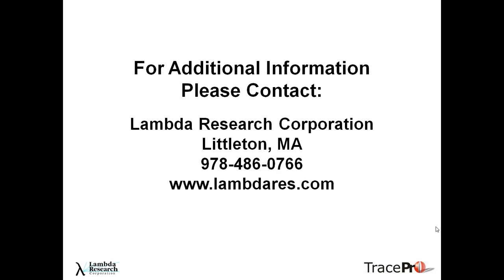We also have a webinar on the website that you can go through, and it talks completely about the Ray files that we use and what the formats are. Our Ray file data has 2 formats: an ASCII format and a binary format. The ASCII format has a 7-row header that specifies that it's a Ray file, and after the first 7, it has row after row of Ray data, which is only 7 pieces of information: your XYZ position, your XYZ direction vector, and the flux associated with that ray. So if you're opening up one of these Ray files, you should be easily able to tell if it's a valid Ray file or not, that we can read it or not.